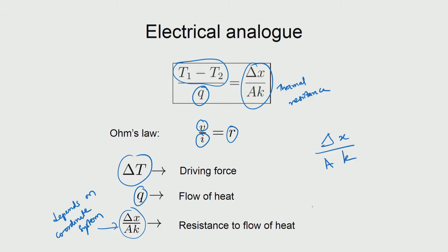What it implies is that if the thermal conductivity is increased, that means it is able to send the heat across very easily. So, therefore, the resistance should come down. If the cross sectional area is large, that means the heat can go across a larger area. So, therefore, the resistance is less, and if it has to go over a longer distance, then that also means that the resistance is more. So, the proportionalities are as we can already imagine from our daily life experience, but we now have a mathematically defined way to look at what is called the thermal resistance.